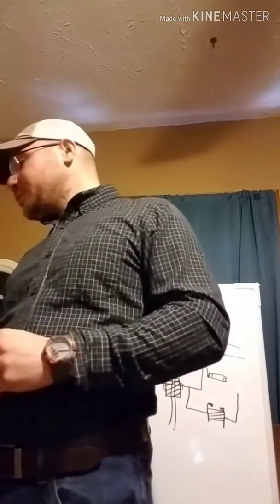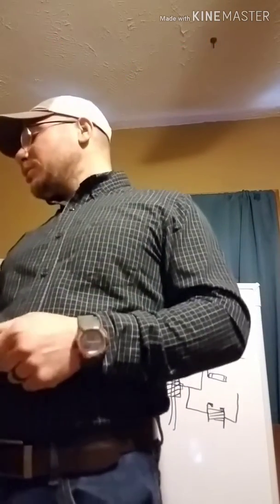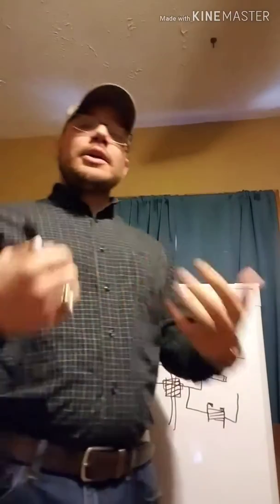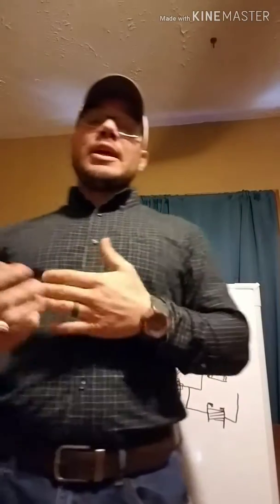We are on splices, 342.56, splice and taps. Splice and taps shall be made in accordance with 300.15. Okay, 300.15 says that it cannot be basically inside the raceway, right? It has to be inside a conduit body or a junction box or something like that. Okay, so it'll be a junction box, all those different things. It can't be inside the conduit itself because splice and taps need to be what? Accessible. Okay, and so make sure you don't wire nut it, pull wire through because you ran out of wire or something and have that splice inside there. The splices have to be in a box.